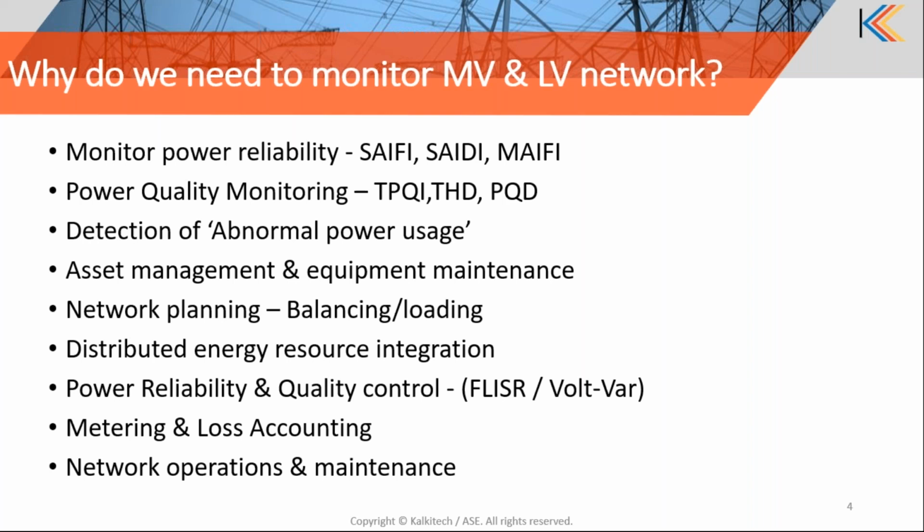Similarly, on the power quality side, we have TPQI, that is the total power quality indices, which is calculated from the power quality measurements like harmonics, interharmonics, voltage fluctuations, flickers, surges, sags, swells of the voltage, etc.